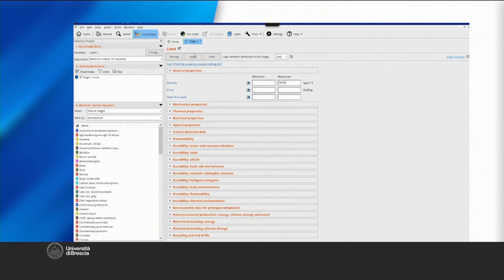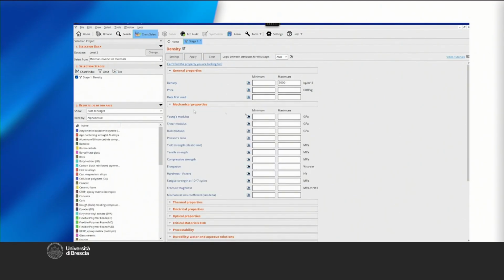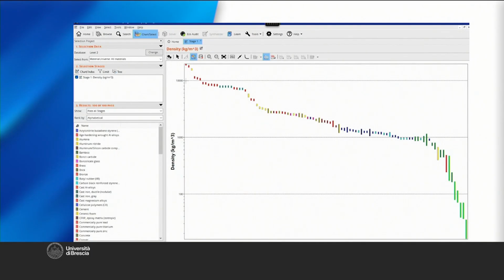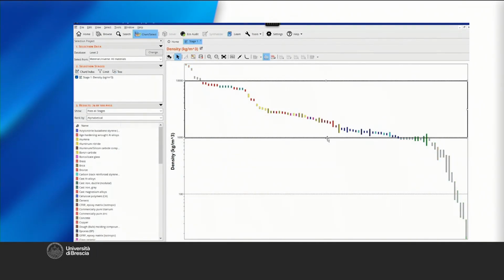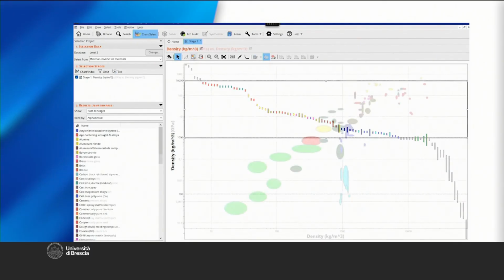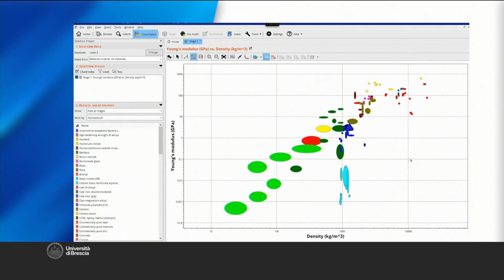Furthermore, it also allows you to graphically narrow down the area of interest, excluding materials that fall outside certain properties. You can then use the indices guidelines to isolate or broaden the selection, focusing on a smaller number of candidates. The software provides both a graphical display and a numerical ranking of the materials with the best performance.